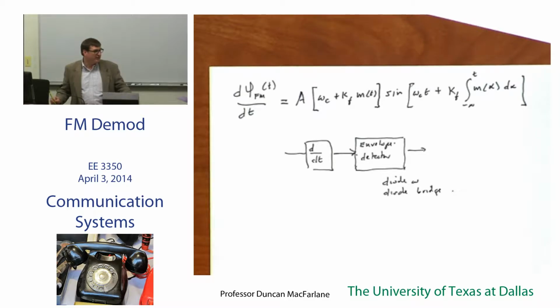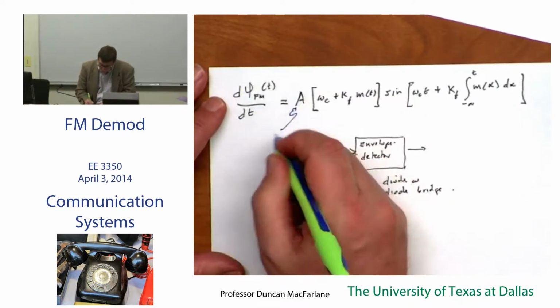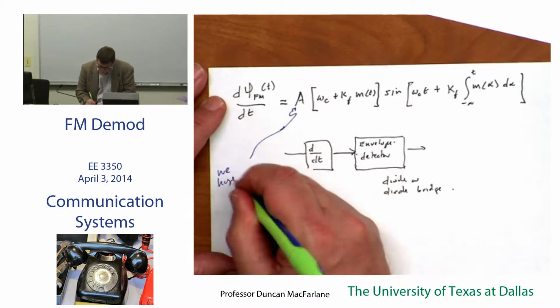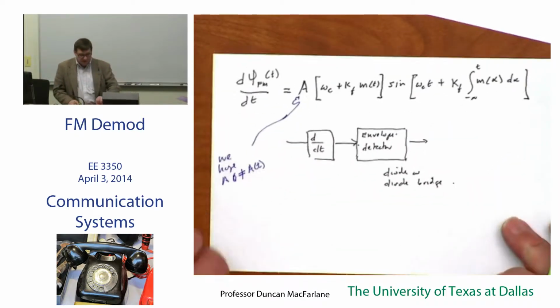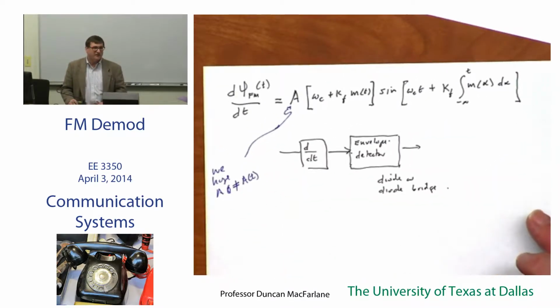What could happen to the strength of my signal? It can weaken. And will that amount of absorption or attenuation or weakening, will that always be constant? No, there'll be all kinds of weird things that'll cause fading in and out, back reflections off of the surface, off of barns and buildings and things of that nature, will cause, in particular, well, we hope that that A is not a function of A of t.